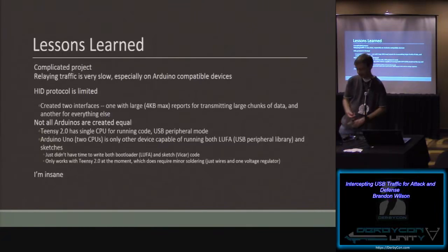Also, not all Arduinos are created equal. To create the Vicar interface, we need to be able to customize the USB connection between it and the PC. And most Arduinos don't do that. They just expose a USB to serial interface for serial debug logging and nothing else. But some variants, like the Arduino Uno, are capable of it because they use a dedicated AVR for handling the USB communication, one which has rewritable firmware. Unfortunately, I didn't have time to work on that, so all this only works on the Teensy 2.0 device at the moment. And the pins don't line up between the Teensy and the USB host shield, so a little bit of soldering wires is required, but just wires. That's something most people can handle.